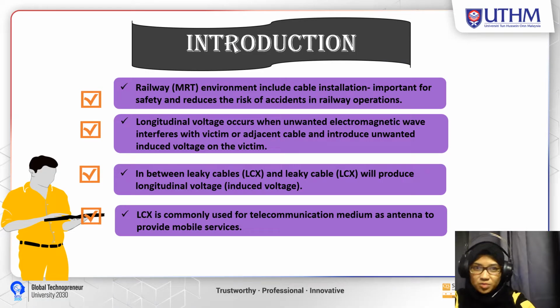The introduction of this project: railway infrastructure includes cable installation that is important for safety and reducing the risk of accidents in railway. Longitudinal voltage occurs when unwanted electromagnetic waves interfere with a victim or adjacent cable and introduce unwanted induced voltage on the victim.